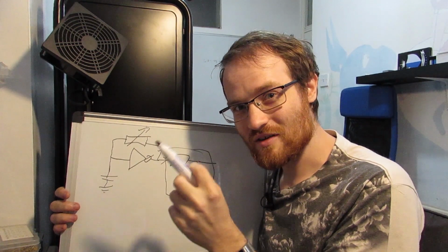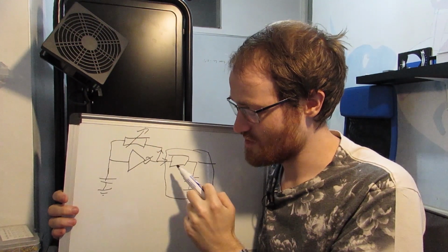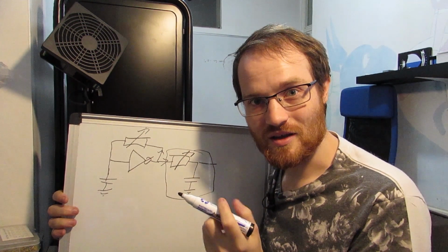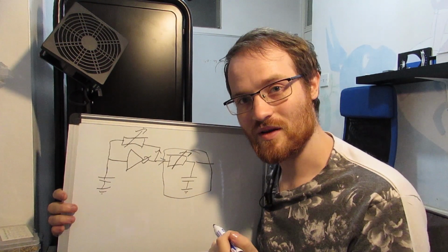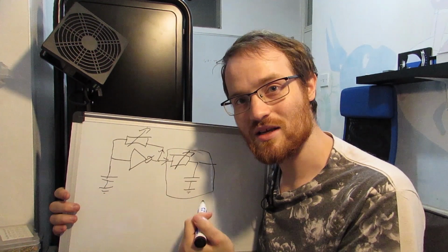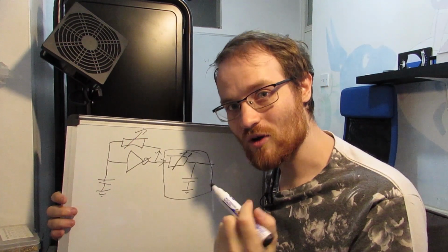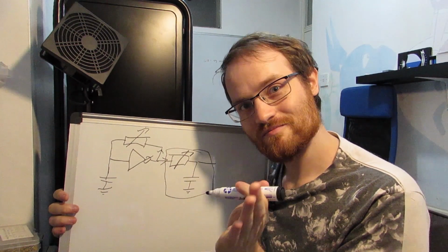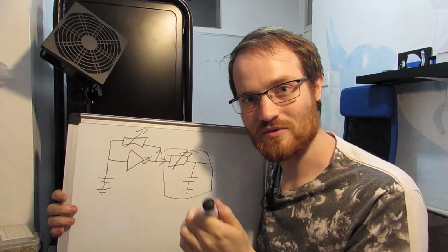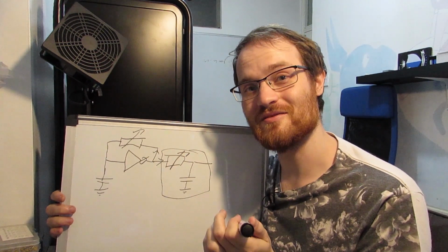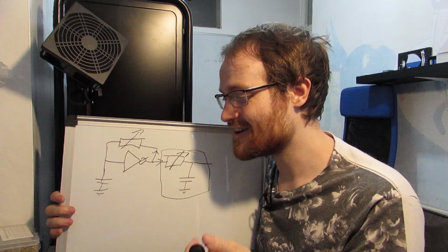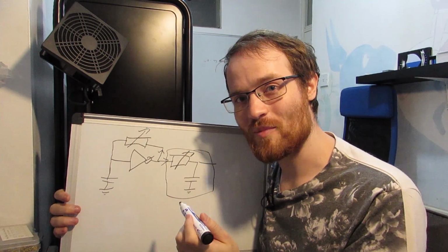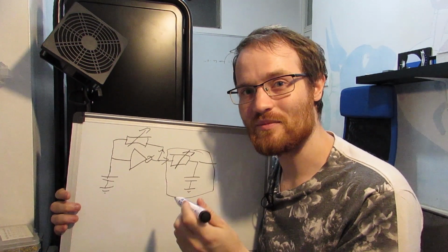So it's a very subtle thing, but as we change this, and if we put a variable pot here, as we decrease this, because we want to change the cutoff frequency, don't we, if it's a filter, and so to change the cutoff frequency, we change this resistance. As we drop the impedance, this loading effect would get worse and worse. So the lowest bound of this would have to be higher and higher, but then the output impedance of this section gets higher and higher as well, so you've got a massive problem. That's why op amps are so good, because the input impedance of an op amp is very high and the output impedance of an op amp is very low.